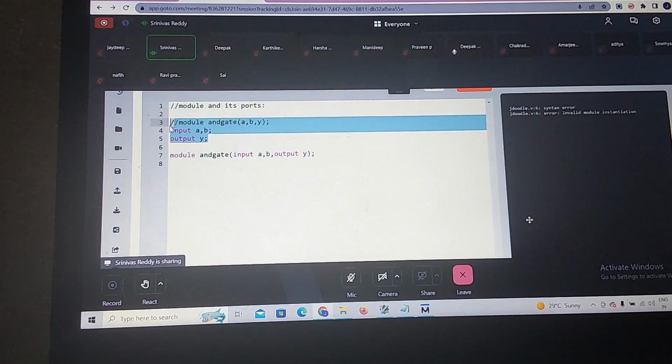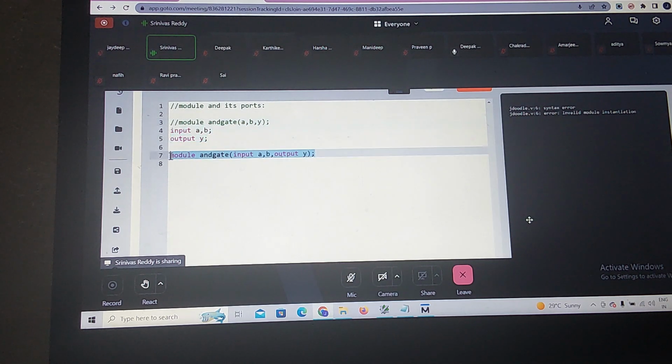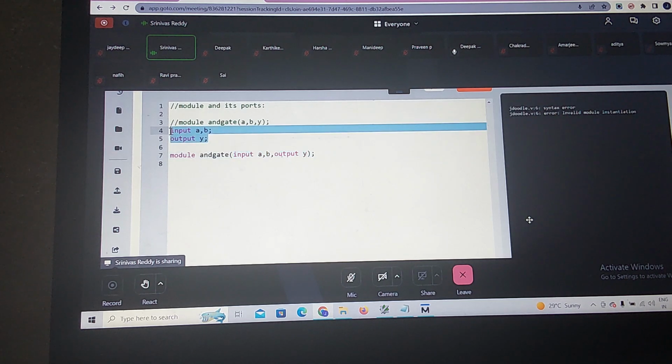If you write this, it is also okay, and this is also fine. You are declaring inside the what? Constructor. Parenthesis is nothing but a constructor. So inside this constructor, you are writing what? Port list with a declaration. You don't understand this. Now what goes inside this?